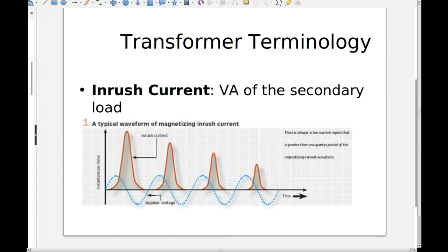Now after that, remember, you're only energizing it during part of the cycle, and during the second half of the cycle you're dumping the energy back out. That's why the current is reducing. You first have to get some energy in the coil, but then as you start building it up, the spikes of current drop because it starts dumping that energy in the other half of the cycle, so it's passing that energy back and forth.